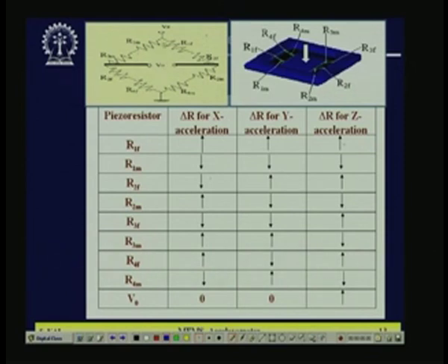Now if I connect this in this fashion, then you can see for x axis, where the first term, we have 1M and 3M connected. Let us look, 1M is reducing and 3M is increasing. So 3M is increasing, 1M is reducing for this arm. So that means if you add these two, one increases, one reduces, so automatically the total value will be the same, the total change will be 0.